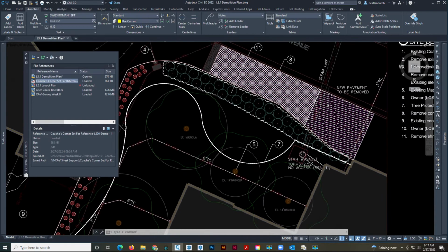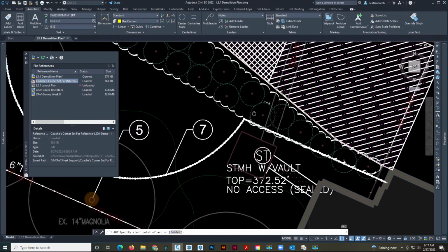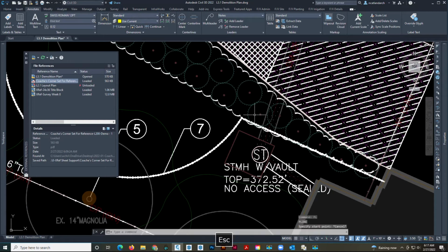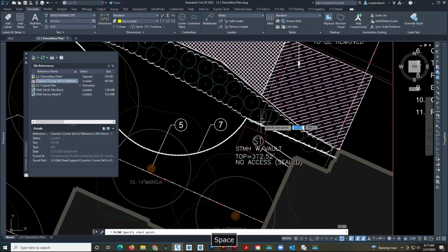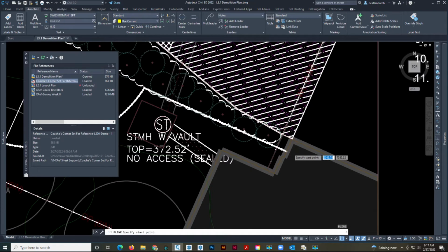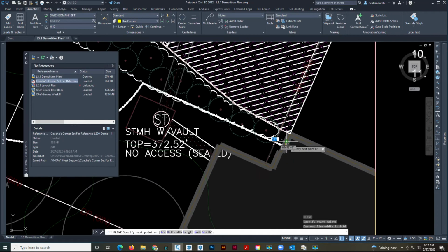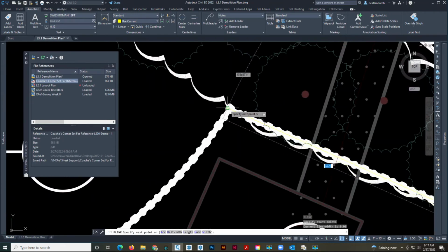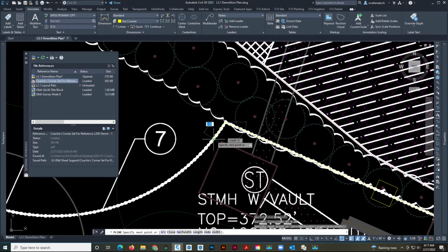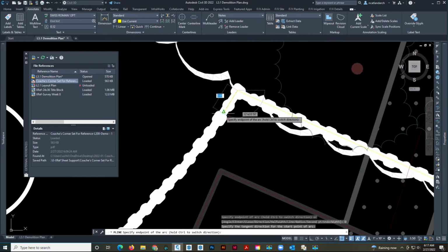All right. So now I will attempt to do these, almost like these arcs for this. Really, it's a polyline, so they're starting here and coming over. So PL, I'm going to come here to the building line, it looks like, and just come out. And it looks like your arcing direction is this way.